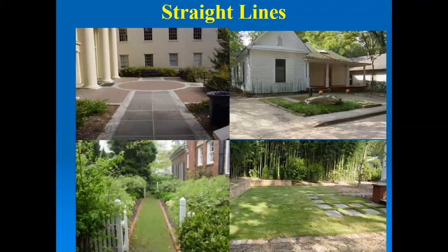These are some more designs. Bed lines should also blend in with the house, driveway, sidewalks, and slope. Experiment with various lines. A lot of times you could just use a hose or a rope and get some turf paint. You can buy those at garden centers and building supply stores, and just spray along the rope or the hose, and you've got your bed line, and that helps you determine what you want.